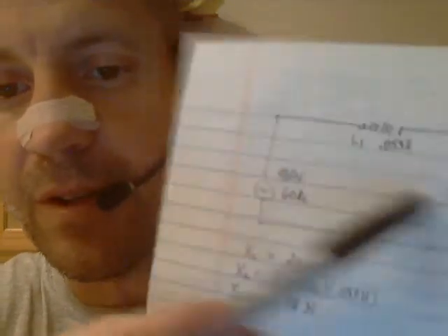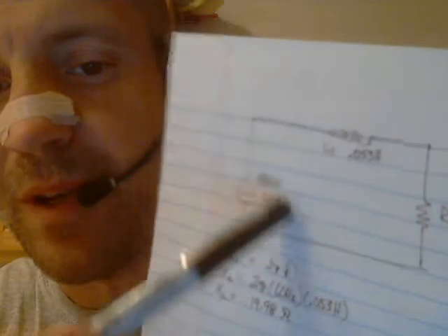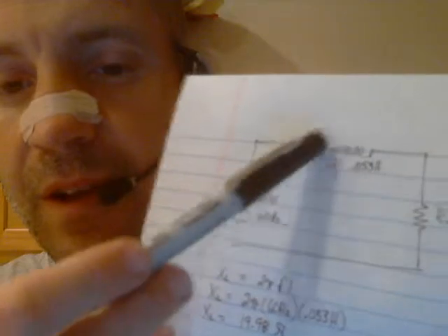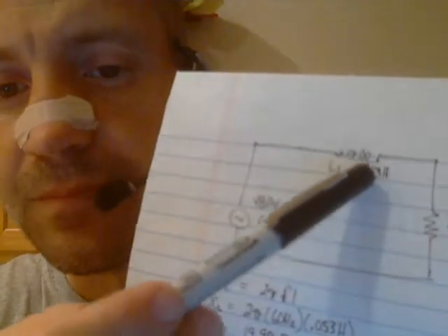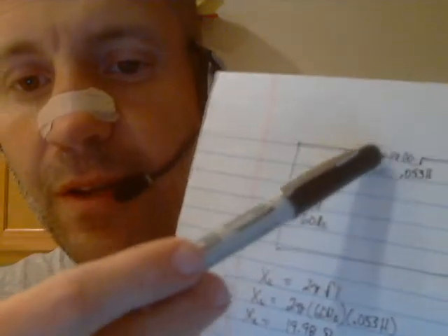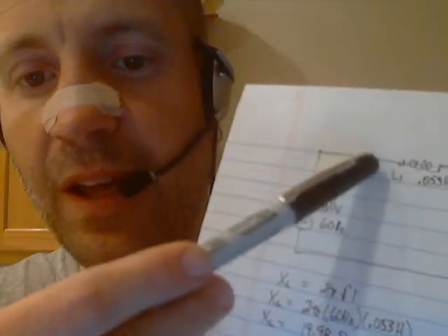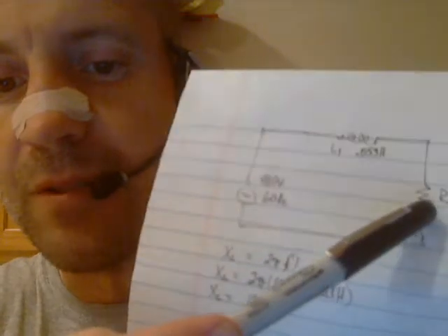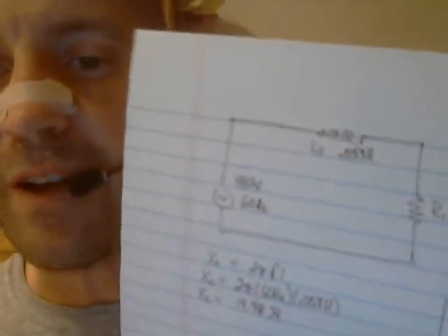Unfortunately, we can't, because the resistor is in phase with the source here, so everything's operating basically in phase. But when you put a coil in a circuit, as far as this coil is concerned, the current is lagging the voltage by 90 degrees. So that means our coil and our resistor are 90 degrees out of phase. The only way we can add these two together is to take vectors into account.